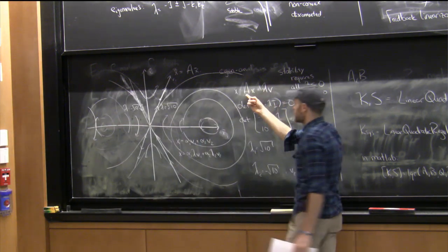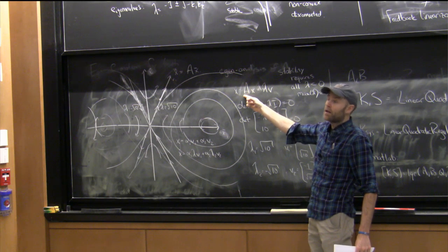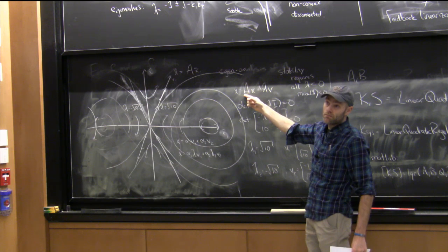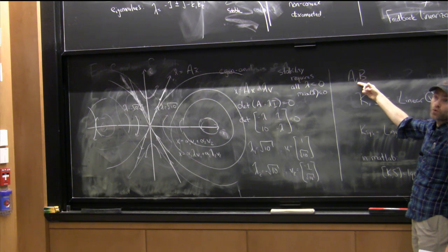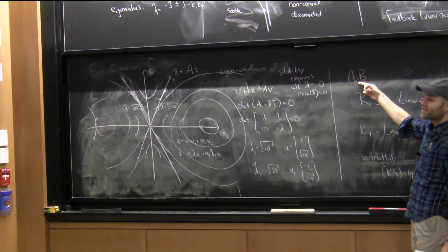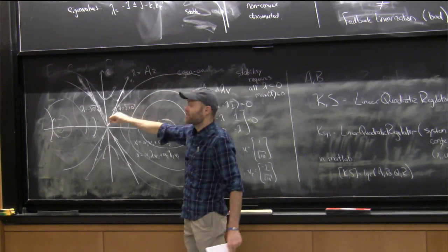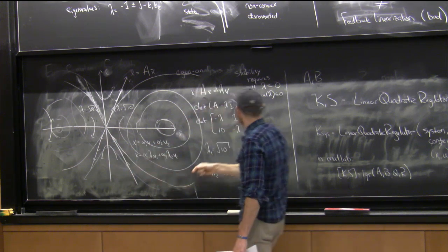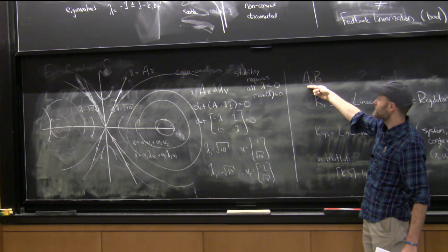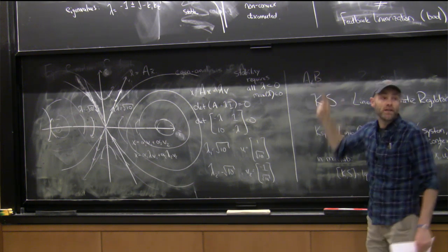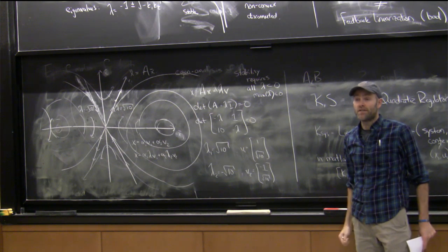So this stability question is just a function of the closed loop system. It doesn't say anything about if you have control input. A related question is controllability, which says if I have A and B, you can ask, is that pair A and B controllable? Which means, does there exist a sequence of control inputs that would take me from any initial condition back to the origin? And for linear systems, that's a question you can ask efficiently. If you've grown up with this stuff, you know the answers. There's a simple condition, and you can just ask whether a linear system is controllable in any standard software package.